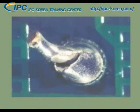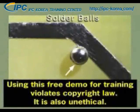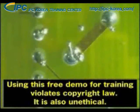Now let's examine the visual defect criteria for through-hole solder joints. We'll look at solder balls first. Any solder balls that are not entrapped in a permanent coating, or attached to a metal contact, or violate minimum electrical clearance requirements are considered a defective condition.